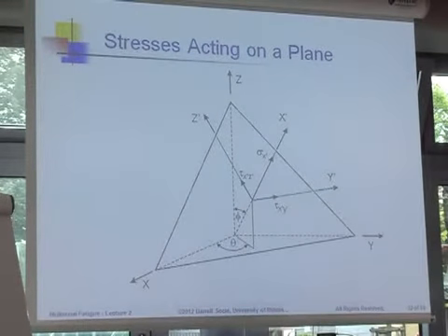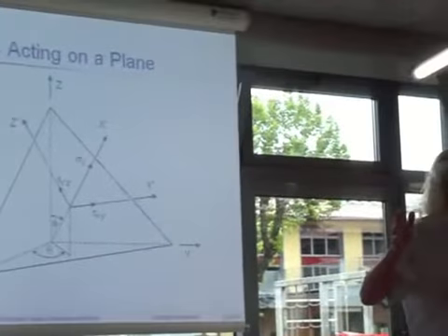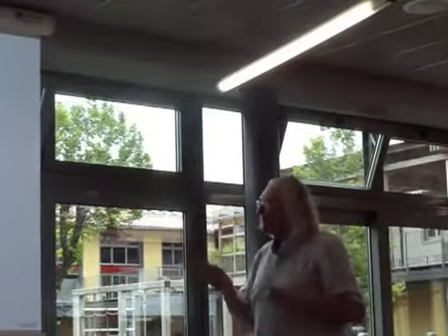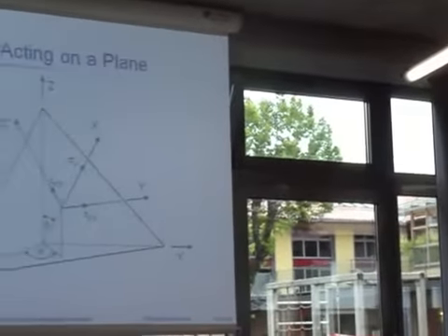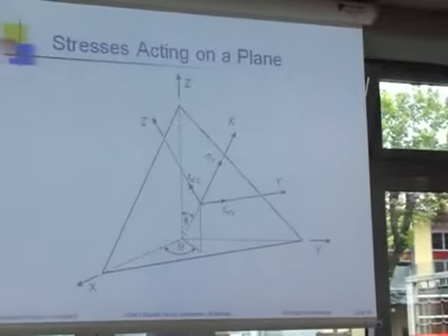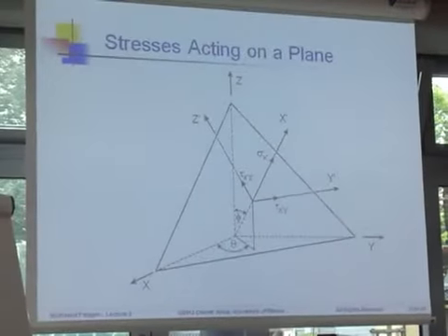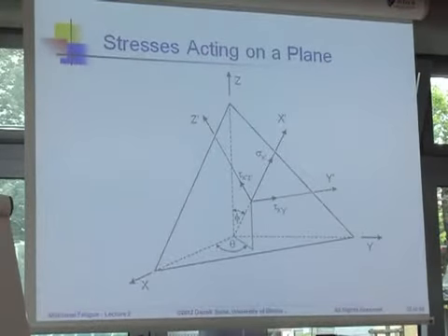Have any of you ever seen a crack growing in random directions? No. A crack grows more or less on one plane, and maybe it will change to a different plane, but it grows more or less planar. So this means that the driving force for fatigue must be more or less planar. And so now if we look at what happens in a plane, so I just draw a plane, then we see that there are only 2 or 3 stresses that you have to deal with.